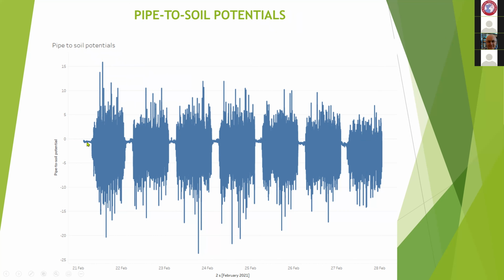And these periods here, these little static periods, that's when the railway's not operating. That's the nighttime operation, which for most systems in this country at the moment is just the period when they're doing the maintenance on the line. So there is a little bit of current flitting around, but you can see that in that period, the pipeline's in the right area to be protected.